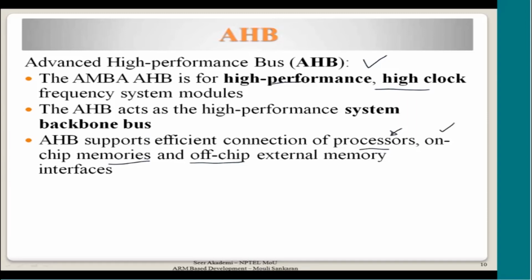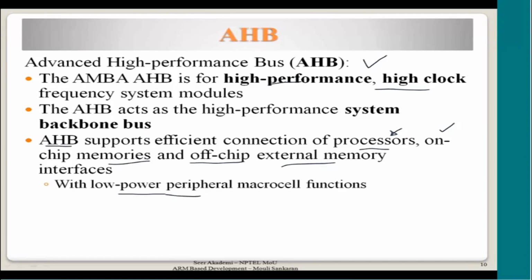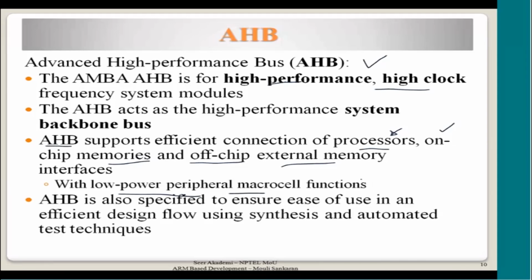On-chip as well as off-chip memories are connected, external memory is also connected to the same AHB bus. The low power peripheral macrocell functions are also there, but may not be connected directly. It could be through the APB bridge that I will talk about later. AHB is also specified to ensure ease of use in an efficient design flow using synthesis and automated test techniques. So it also has an easier design flow, so that you will be able to integrate the modules, different peripherals, processors or memories